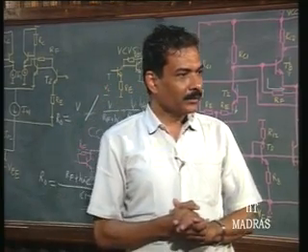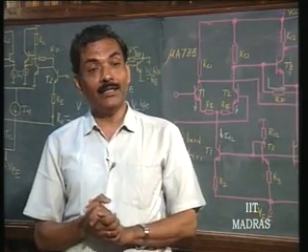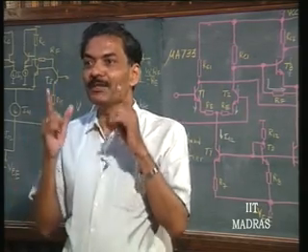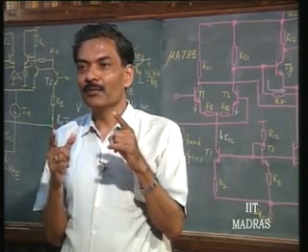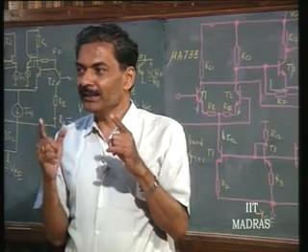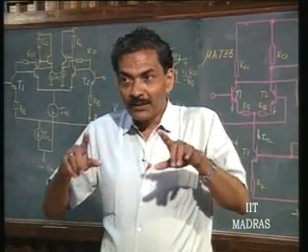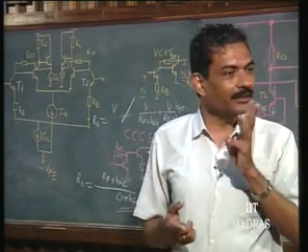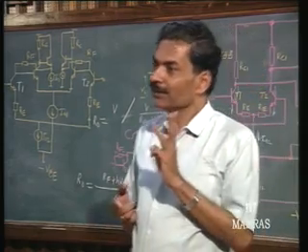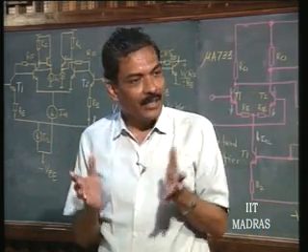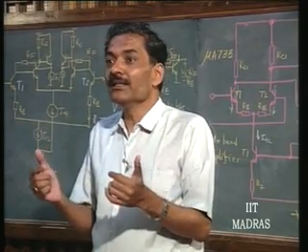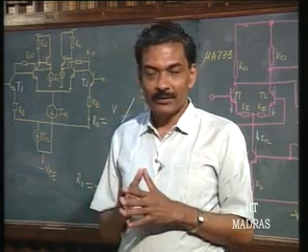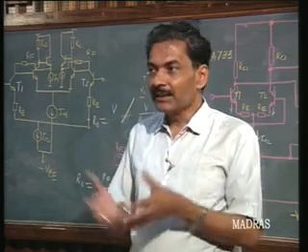Now, in the next class, we will see why not go for two stages. You just said single stage is the most preferred stage because what? The order of the system is going to be 2. If I go for 2 stages, the order is definitely going to be 3, and it is likely to cause serious problems of oscillation when using. This is what happens, right? Even in IC amplifiers, we have 2 stage amplifiers, but they will require external frequency compensation in order to maintain them stable. Frequency stability is what we are talking of, and we will see such structures